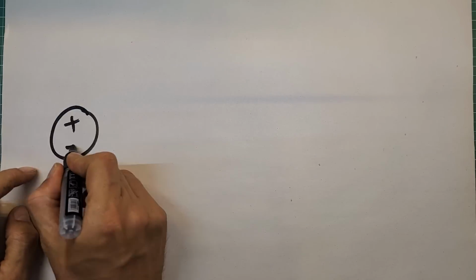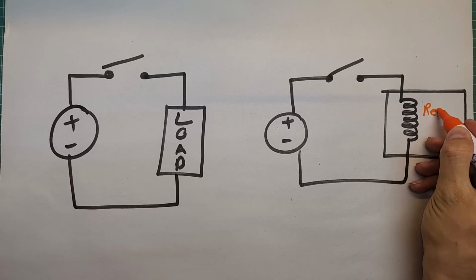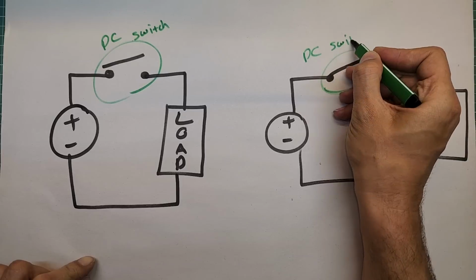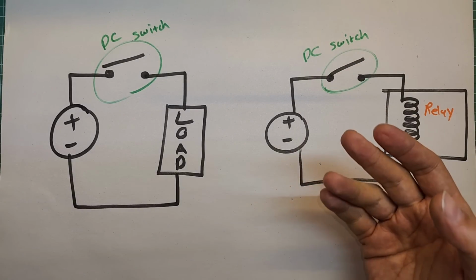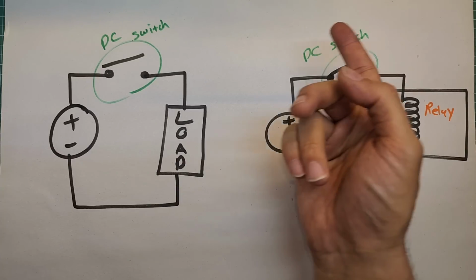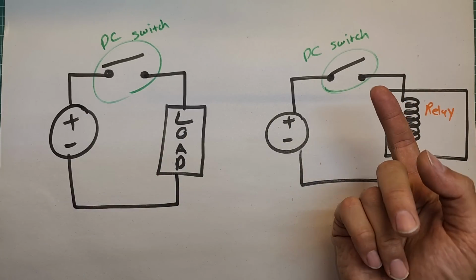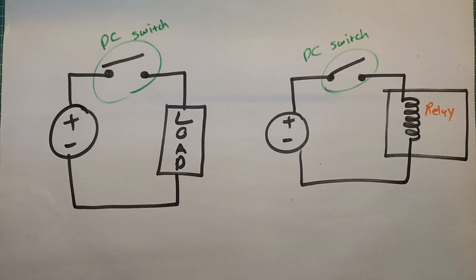As I already mentioned, BJTs and FETs share a significant overlap in their application, especially when they are employed for switching loads at lower frequencies. By low frequency switching, I refer to scenarios where the number of on-off state changes per second is low. For example, if you are going to switch a DC load at low frequency, it really doesn't matter if you use a BJT or FET. In scenarios like this, non-technical parameters like cost or availability in the market will affect your choice. Scenarios like that are not the subject of this video, so let's not lose time and move on to the first difference.